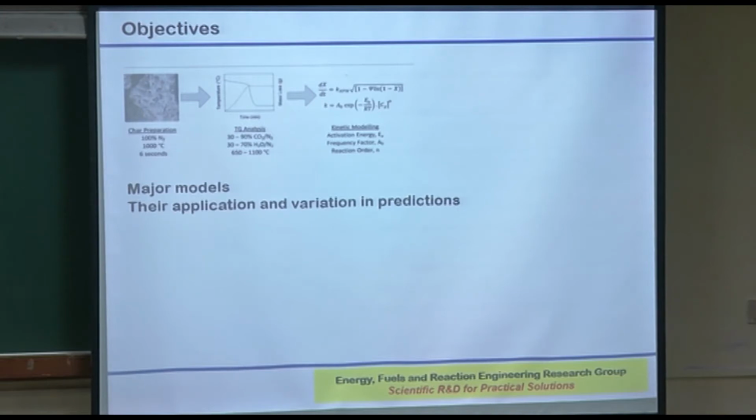But if you are operating the gasifier at 1300 degrees, then within 7 seconds, not 24 seconds, you can get full carbon conversion.